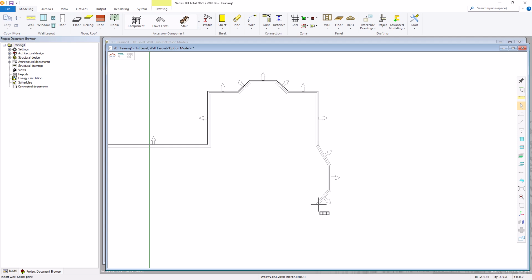For the next segment, we need to go back this direction. So again, it'll be 4 feet down from the Y, and from this Y axis, we want to go back 30 degrees. So we'll make sure that we are off the constraint icon, and again 0 for the X, and we'll remove it and type in -4 feet.